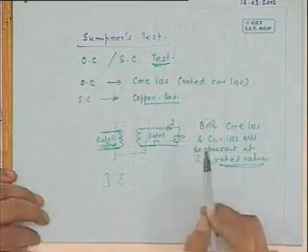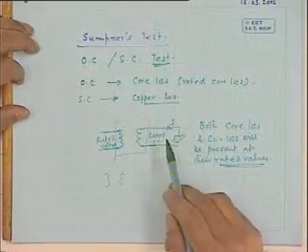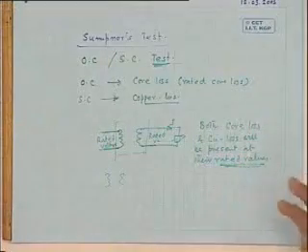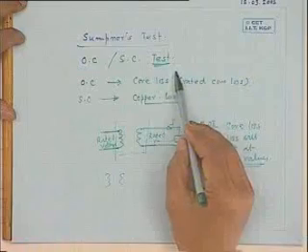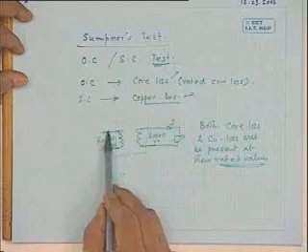That is, you really operate the transformer by connecting some impedance so that it fully loads the transformer, and see your wattmeter readings, ammeter readings, etc., whether the windings are capable. One point is very clear: neither the open circuit test nor the short circuit test alone will give you the appropriate temperature rise in the transformer, because the other loss is completely absent in either test. But in the load test that is possible.